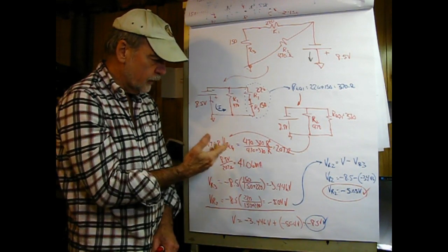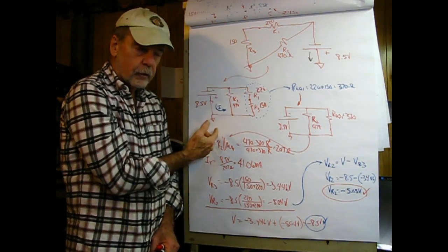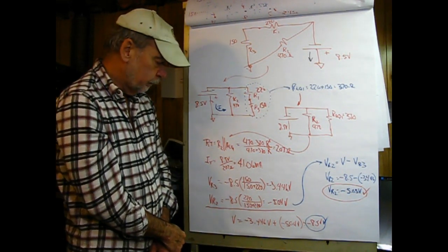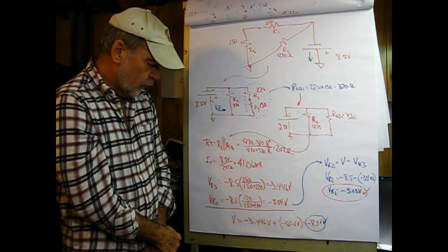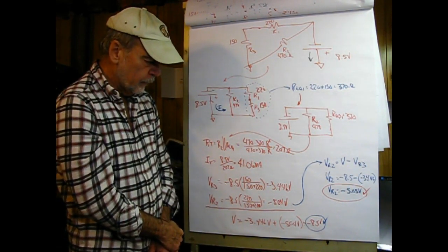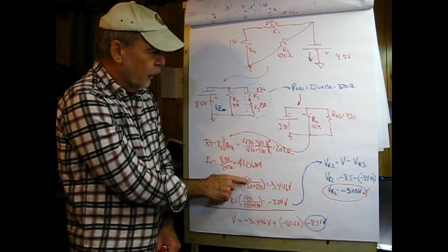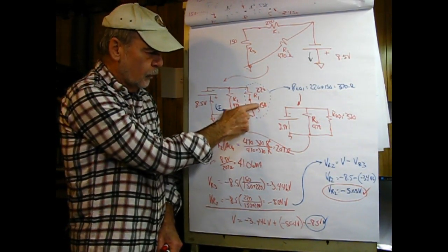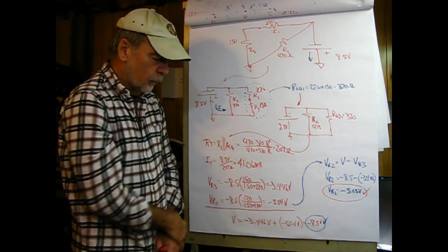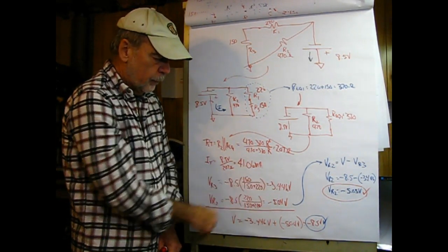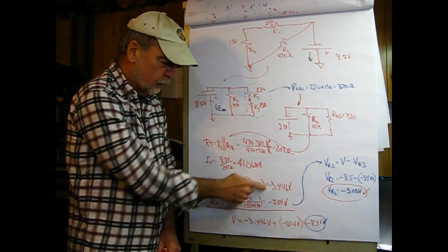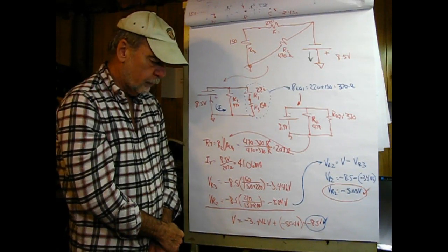In some circuits, you have to be very, very careful of that. If the direction of the current flow physically is the same as the definition of the current flow, then it's a positive current. So next I want to find VR3, and this time I'm going to take negative 8.5 volts, and across this here is going to be the 150 ohms. I want the voltage across this resistor, and that's going to be divided by our total, and that now equals negative 3.446. So you have to be careful that you don't drop the sign on this. It would be a negative voltage referencing ground.